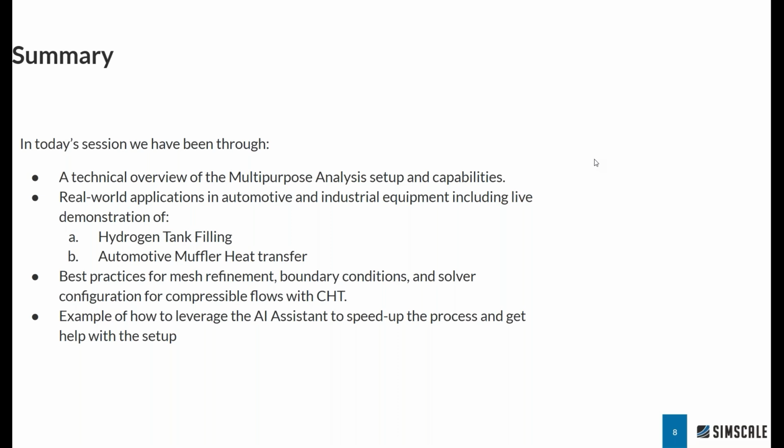We saw best practices on how to prepare the geometry for simulation, how to prepare the mesh with relevant refinement zones or manual or automatic sizing. We saw the different boundary conditions and different solver configurations that are applicable for compressible flows with our new multipurpose conjugate heat transfer mode. Finally, we saw how, with the help of the AI assistant, we were able to get help on the setup. So if we were new users, we could easily utilize the help taken from there to help us set up our first simulation with minimum effort and confidence.